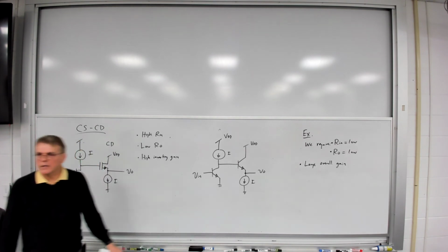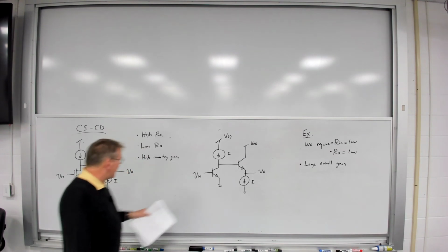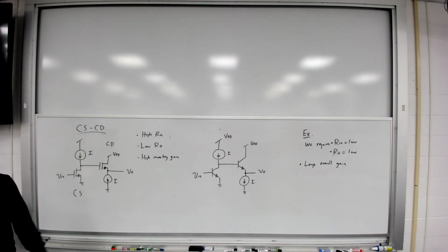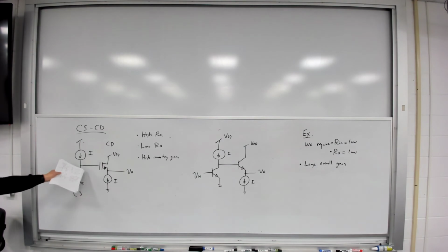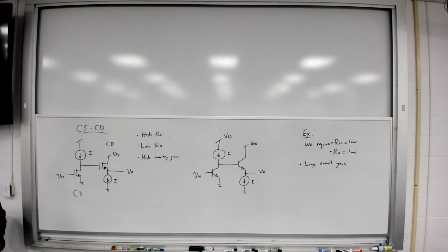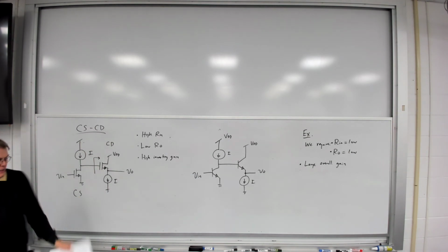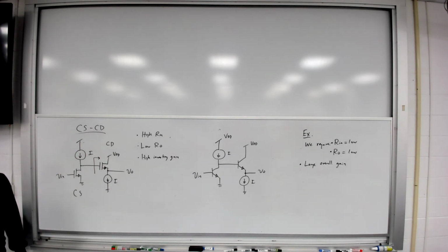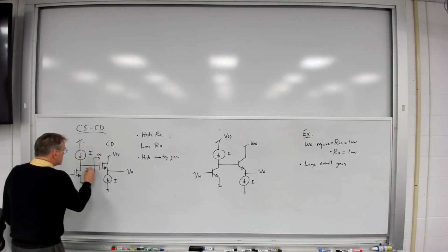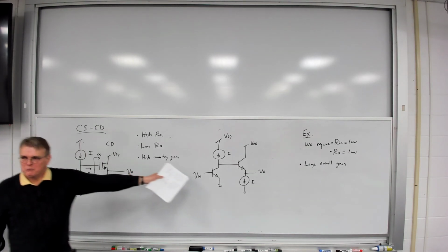So I can do the same kind of trick here with a BJT that I can with a MOSFET. But this is a somewhat trickier design than this design. It's a little more difficult to do that design. Can anybody tell me why this design is trickier than that? Anybody want to venture a guess? Well, let's think about this. What's that input resistance, theoretically, looking into that second stage? It's infinite, yeah. What is the DC current going into that second stage? 0.